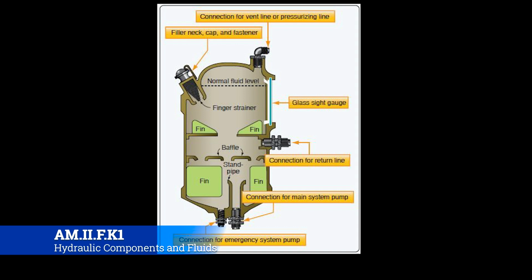Now, a bathtub doesn't have any baffles in it because you've got to lay down in it and take a bath. But say that bathtub was in an RV, and that RV hit a bump. All that fluid would go sloshing around. Think about it weight and balance wise. If a lot of fluid goes from one end, you've changed the CG of that component, and therefore the CG of the apparatus that's holding that component. In a fuel cell, all that fuel rushes to one side and causes the plane to behave a certain way, and then, action and reaction, it wants to rush back, maybe to a lesser degree, but it still causes the CG to shift again. All the while, it becomes really, really difficult to control.